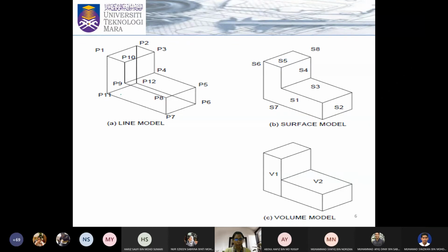So the first picture over here speaks about a line model, which simply reflects to a wireframe model. So this is nothing but a connection of points with edges. So this will just basically be lines. Now all three models, the purpose and the objective is to give us a visual representation in three-dimensional space. So the wireframe model is the simplest and easiest representation, right? But it can create ambiguities, like you can see over here. You do not know whether this is from this side or it's in the internal side. It can give you a rough idea, but not the full idea.